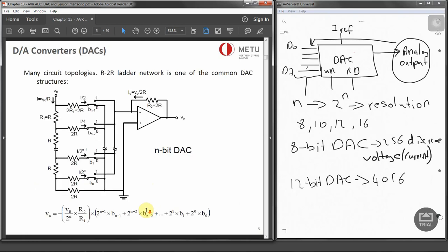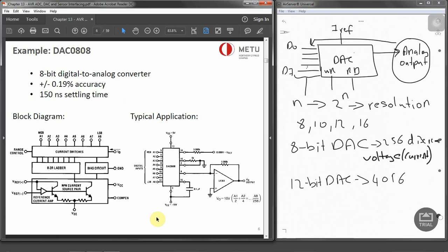So over here, what we can ideally do is connect the output pin I-out to a resistor to convert this current to a voltage and monitor the output on the scope. However, in real life, this is not a really accurate way of doing this, because the input resistance of the load where it is connected will also affect the output voltage.